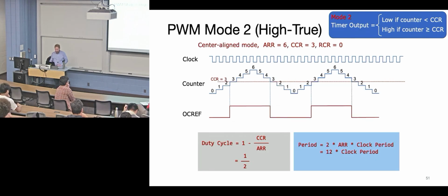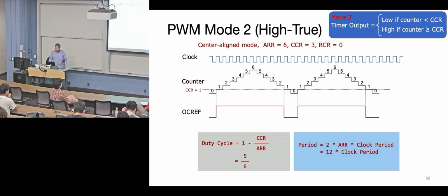And again, if you're going to do timer mode 2, but in the center modulated mode, you could set wider things. Personally, I don't know how often I've ever used this mode. Maybe it's just because my brain doesn't think about it this way. But I'm sure there's good reasons why the fine engineers at STM decided to make sure that this was in this piece of silicon. I guess in this sense, you could go for twice as long if you really wanted to max out your period. You could just double it, but it feels like you could just change your prescaler too.